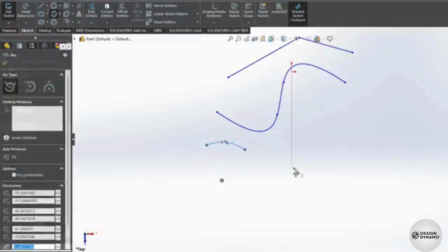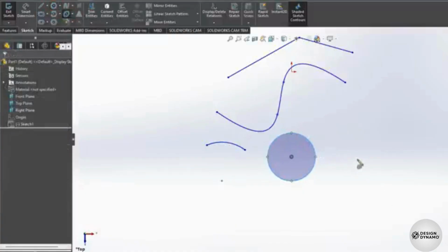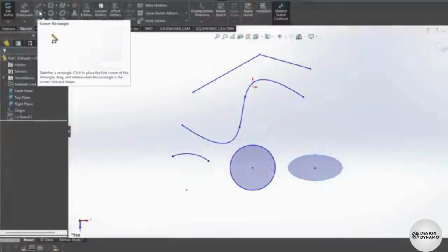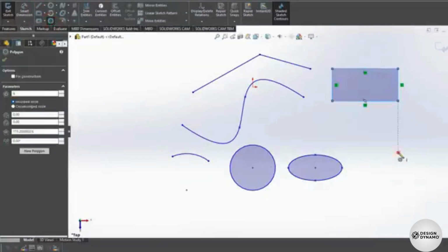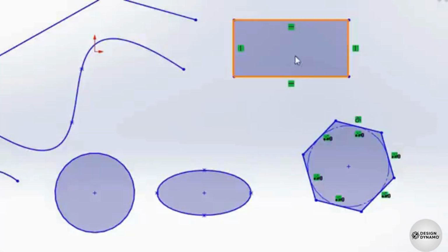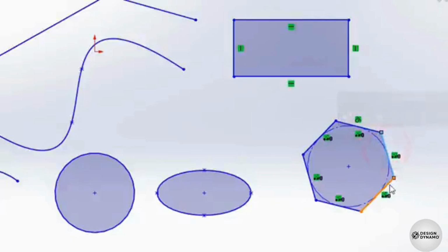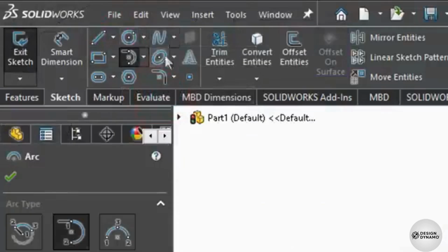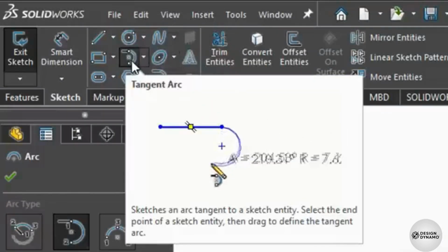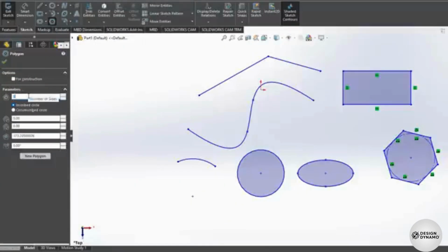arc length. Enable the Circle and the Ellipse tool to drop circles and ellipses with 2 or 3 points. Whereas use the Rectangle and the Polygon tools to drop regular shapes by clicking twice. Consider that all rectangles and polygons are simply groups of straight segments combined together. Each 2D tool includes other drawing modes under the down arrow. You can hover over the main button to get useful tips. Furthermore, the Property Manager on the left allows to change the drawing mode as well as the drawing properties, such as the sides of a polygon.